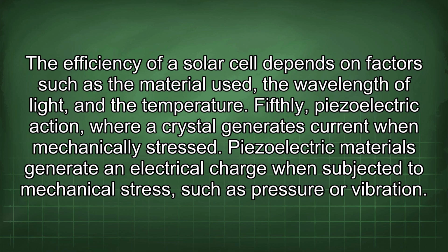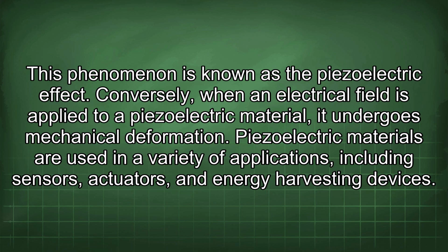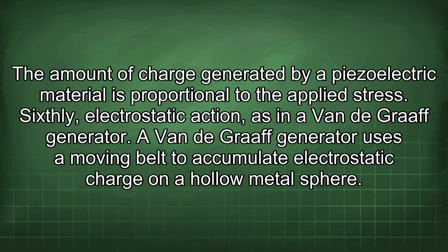Fifthly, piezoelectric action, where a crystal generates current when mechanically stressed. Piezoelectric materials generate an electrical charge when subjected to mechanical stress, such as pressure or vibration. This phenomenon is known as the piezoelectric effect. Conversely, when an electrical field is applied to a piezoelectric material, it undergoes mechanical deformation. Piezoelectric materials are used in a variety of applications, including sensors, actuators, and energy harvesting devices. The amount of charge generated by a piezoelectric material is proportional to the applied stress.